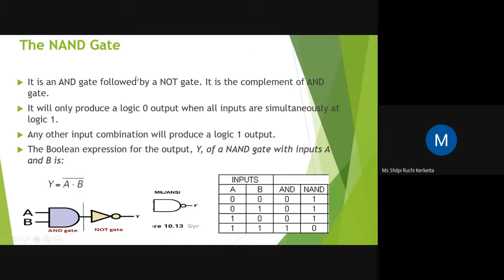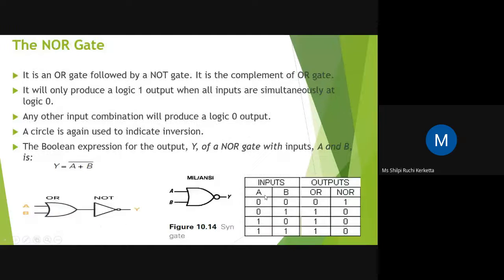The basis of the bistable is the NAND gate and the NOR gate. Let us see the truth table of the NAND gate. What is the truth table for the NAND gate? We are getting 1110. But mainly we are using the 00 and 11 conditions, for both the NAND gate and also the NOR gate. So the truth table is 1000. The inputs we are using are 00 and 11. For 00 we are getting a 1, and for 11 we are getting a 0. So these are the basics of the bistable.